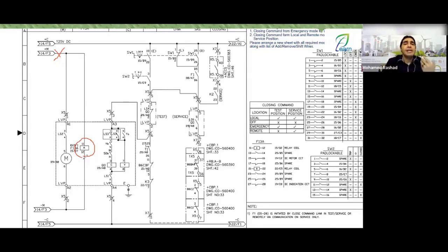In this case, engineers, what do we call this? Its function is called a DC supervisor. This means monitoring the circuit, specifically the positive and negative only. Focus on my words: only. When we move on to another circuit, you'll understand what only means. This also means that if you have a cut in this wire, it won't inform you. It assumes that this wire is coming here and from the same terminal block, it exits here and continues like this.